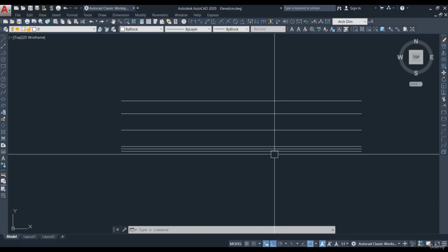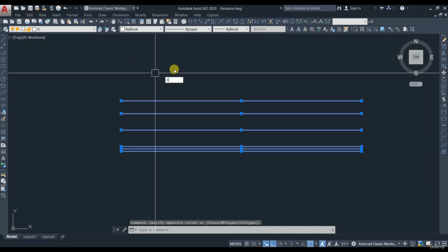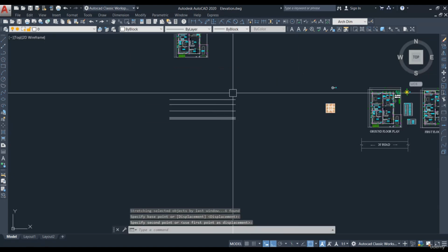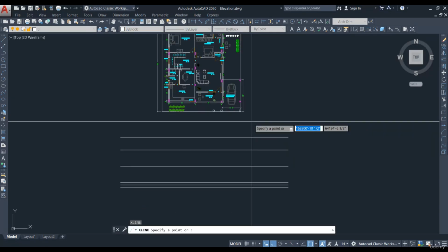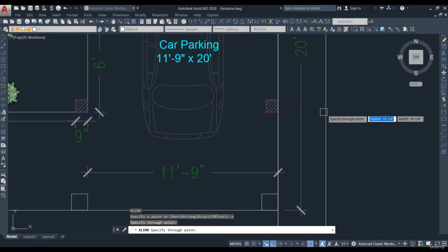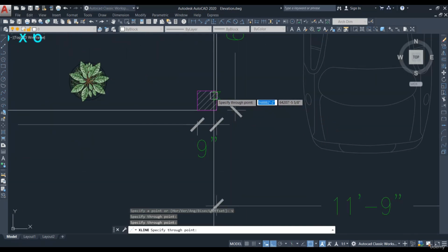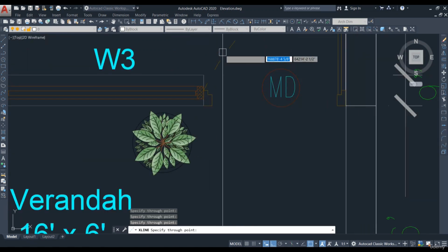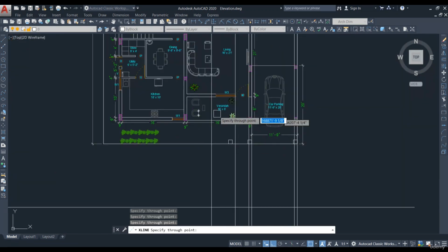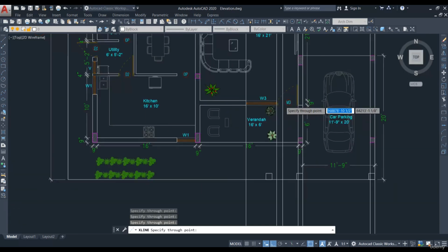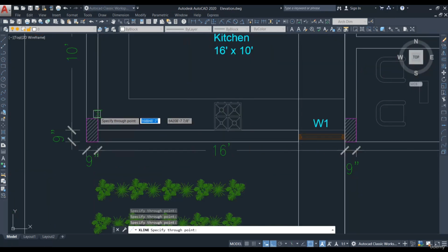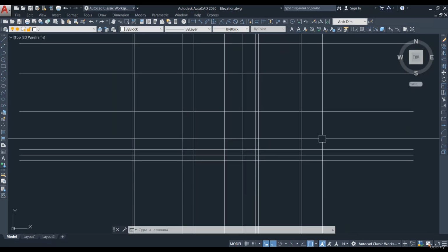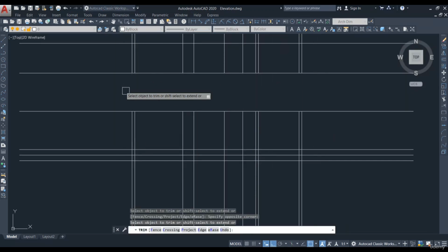So in this level we have to draw the elevation. This even we can reduce like this. Now we can just bring down this plan. Let's use the construction line command, V for vertical lines, and then just take this one. This door, we'll be seeing this door, window, this window, and here this window and then this wall. Now let's use the trim command and trim the unwanted lines.